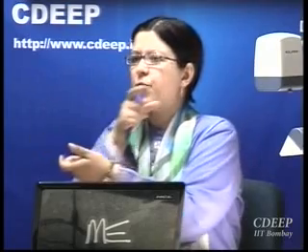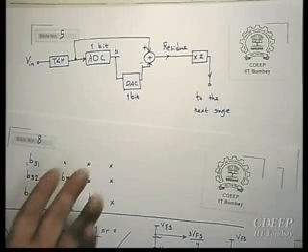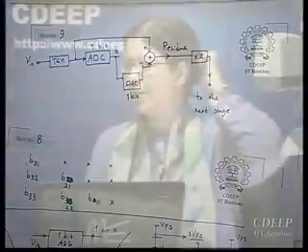It's not very difficult, because in switched capacitors you can make an amplifier with a gain of perfectly 2, a ratio of 2 capacitors. And by changing the way you do switching, you can change the polarity. Therefore, you can make a subtractor, the same way we did here with the SAR ADC. We subtracted signals, right? Just by proper switching, you would be able to do it. Therefore, implementation is not a big deal.